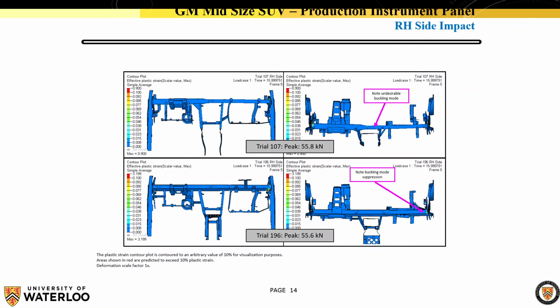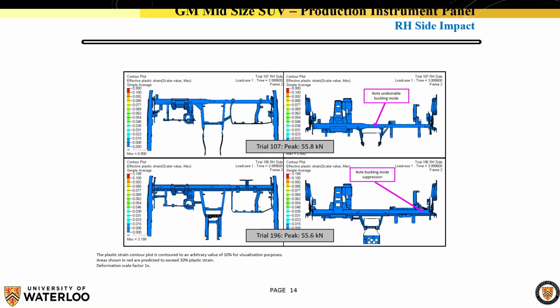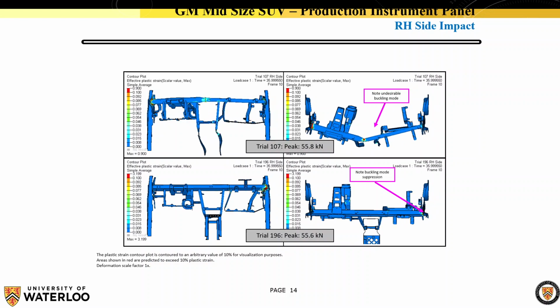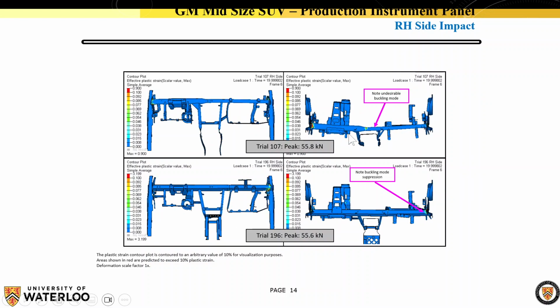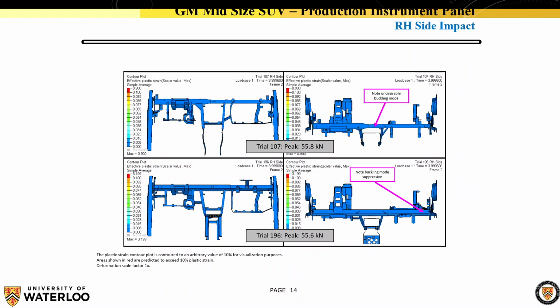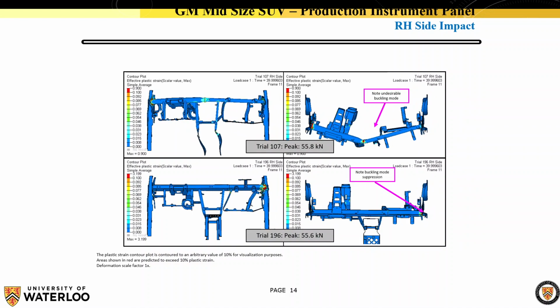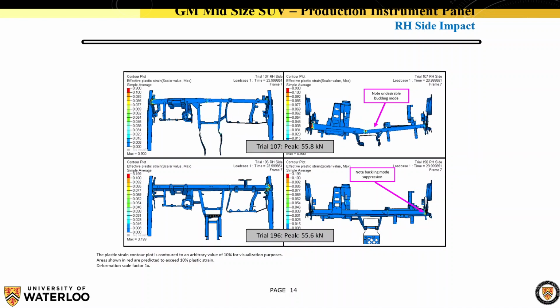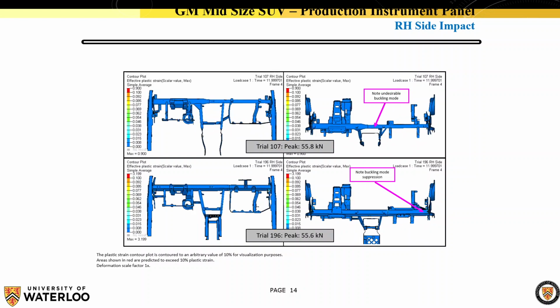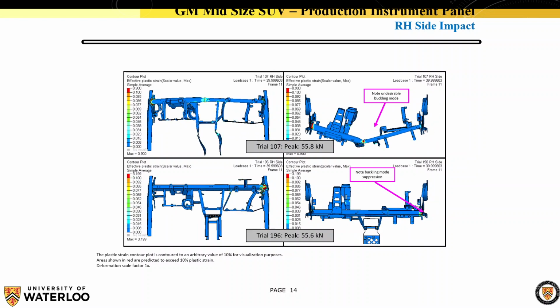People think that the car is symmetric. If you get hit from the left, it's better than getting hit from the right. In this case, it's actually worse. You'll probably sustain more injuries if you get hit from the passenger side just because of the way that the existing structure would buckle.